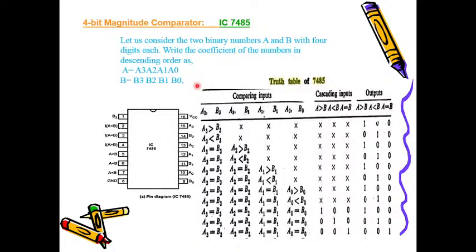After that you have to draw the block diagram. You know already, since I have taught that, but still I will write it. Second step is what? Block diagram. It is a 4-bit magnitude comparator. This is a block you are going to design. And how many outputs? Always 3 outputs: A less than B, greater than, equal.